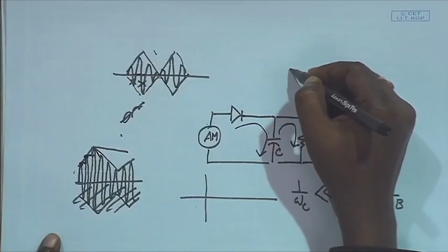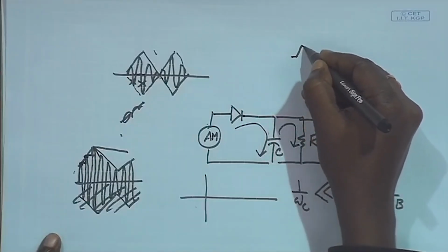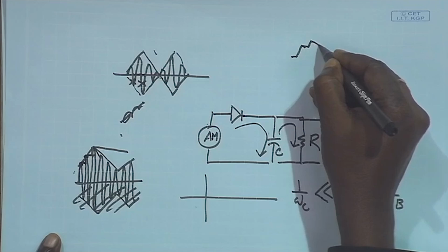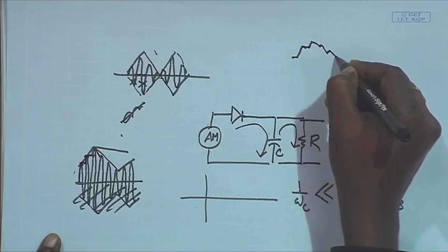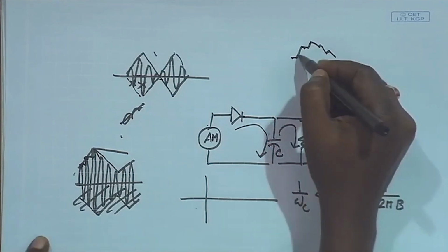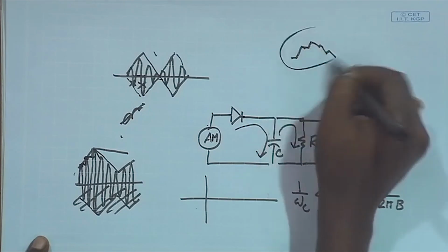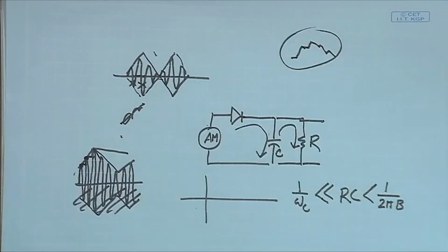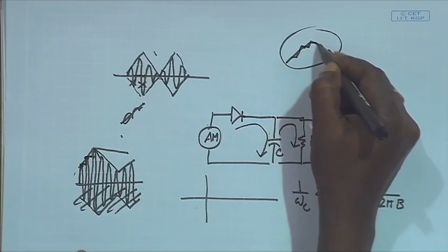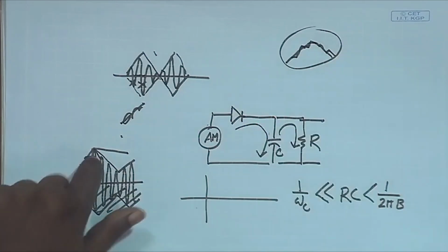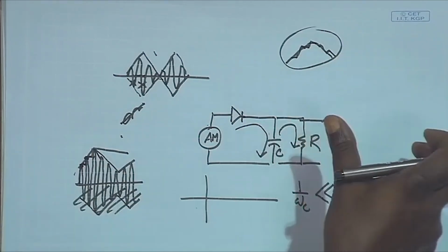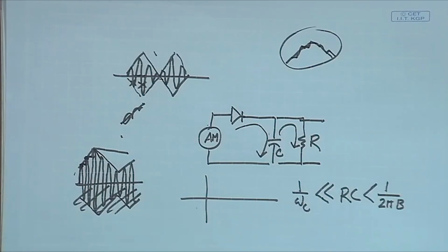So finally my signal will look like this, which is almost tracking the signal. After that there are some aberrations, and just a low pass filtering will make it smoother. So immediately I get this. This, followed by another low pass filtering, will probably smoothen the envelope, and of course there should be a DC blocker.